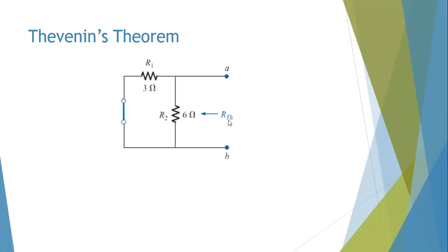And now next we find what resistance you would measure if you look from this side. This is typically how it's shown. If you look from this side with your eye, what resistance would you measure here? The technique I use is I send a current I here, and then you see how this current behaves. The current is going to split into one path here and a second path. So these two are actually in parallel. And of course, these two currents I1 and I2 would merge back to get to capital I here, the same current returning back.